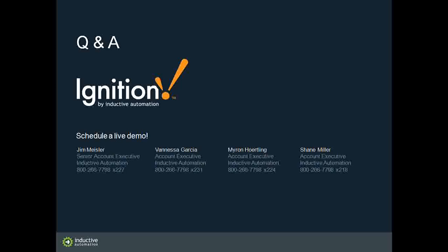This is a little expansion on that question, but you started to answer it anyway. What plant floor control system changes are needed to implement OEE downtime? Okay. At a minimum, you need to know what your outfeed production count is. That gives us our performance on our OEE, and then you also need the process or production line state. So is it producing product or not? At a minimum.